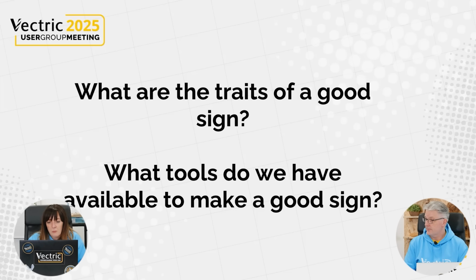So to do that, I'm going to grab this circle right here, and I'm just going to drag outwards. You're going to see now I get a negative radius there. So I'm going to go to about 1 inch. That's great. Press escape, close this down. And now that's definitely not centered in my job space. You could press F9 to do that, or I could go over to my alignment tools and just align that to the center of my sheet.